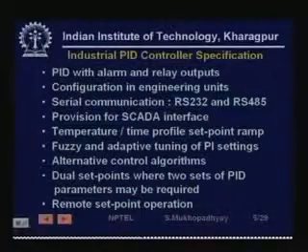So, such facilities have been provided here. And finally, you could have remote set point operation, where basically this remote set point is actually a subset of SCADA. So, if you have supervisory control from a remote place, then you could give set points, maybe the operator sitting in the control room can give set points.